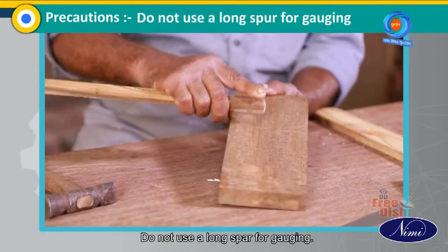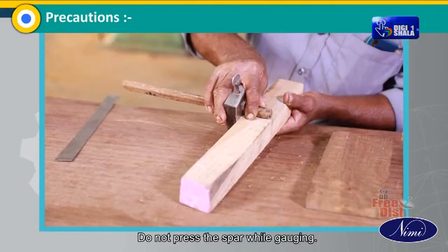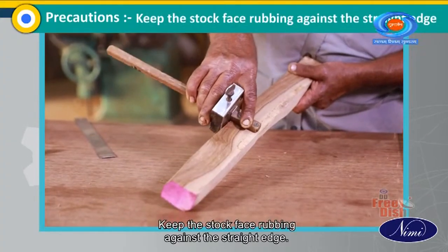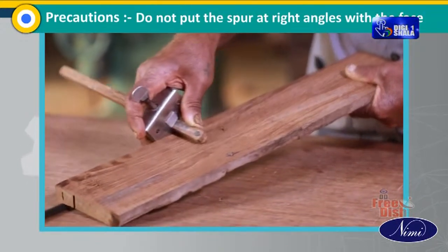Precautions: do not use a long spur for gauging. Do not see the distance by keeping the rule flat. Do not press the spur while gauging. Do not try to make a deep gauge. Keep the stock face rubbing against the straight edge. Do not put the spur at right angles with the face.